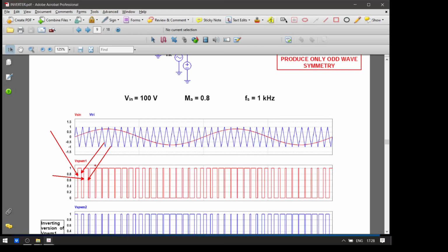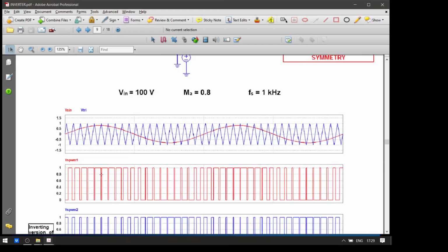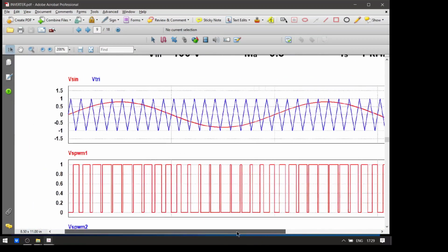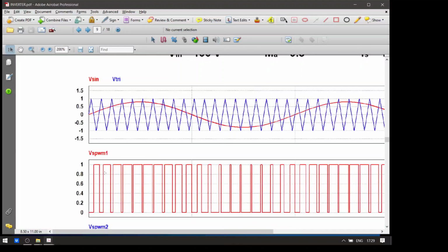So once we have the general equations to describe all these pulses, then you can easily tell the microprocessor to generate the pulse at certain angles. Right. Okay, so the idea is, when you want to look at the details of the analysis of this PWM, the basic thing is we need to establish an equation that defines the positive slope of the triangular carrier signals and the negative slope line for the triangular carrier signals.